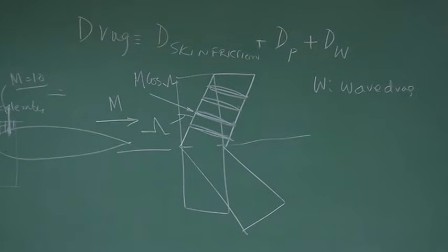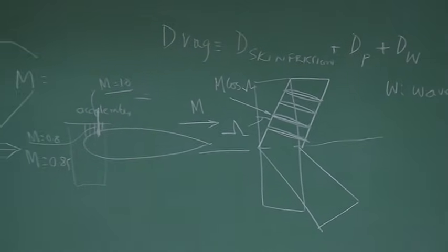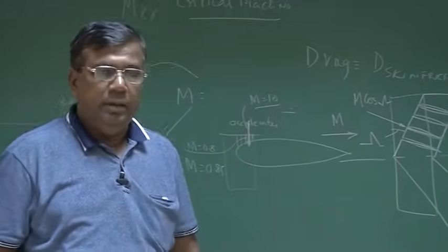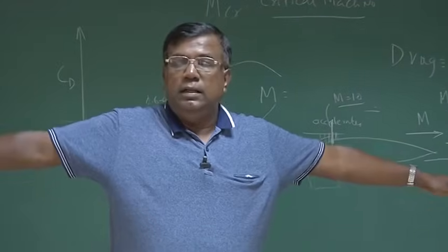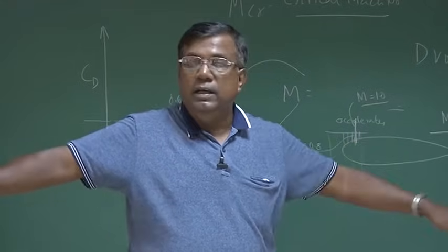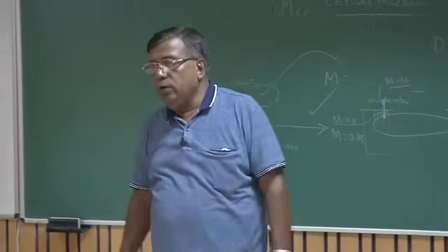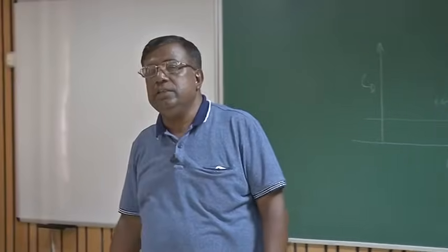You must be aware, you can do a Google search, you could see the Russian MiG-21 BIS. It has a variable sweep. That is, initially sweep is almost 0, and then as it increases speed, it introduces a sweep back. Right? That is where it tries to optimize the aerodynamic efficiency.